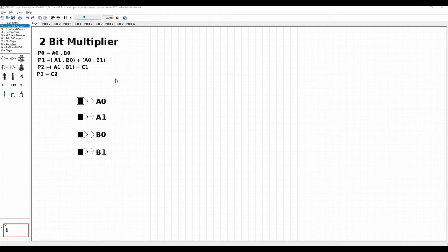So here are all our inputs, and we can say there are 4 AND operations in here, in here, in here and in here. So we have to get 4 AND gates. So let's get the first AND gate, and for this AND gate the inputs are A0 and B0. So let's connect it. I use a connector here.